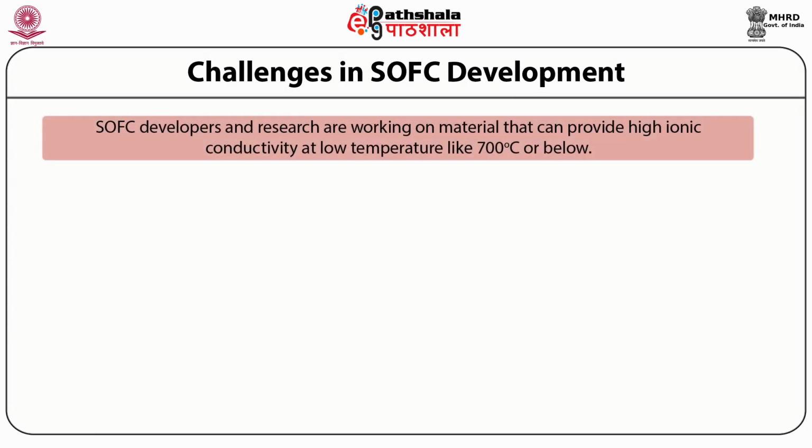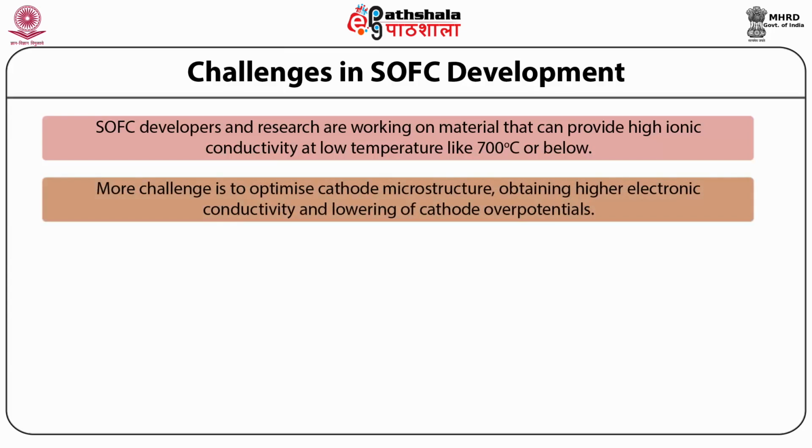Challenges in SOFC development. SOFC developers and researchers are working on materials that can provide high ionic conductivity at low temperatures like 700 degrees Celsius or below. This will significantly reduce the cost and simplify its operation compared to high temperatures. More challenging is to optimize cathode microstructures, obtaining higher electronic conductivity and lowering of cathode overpotentials.